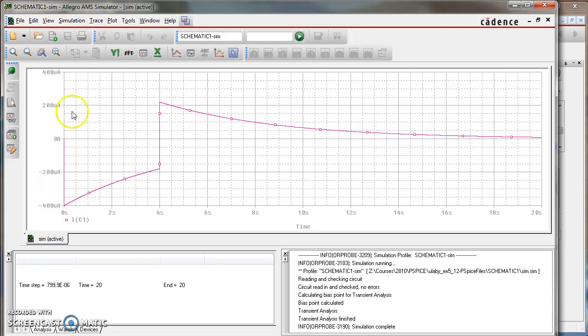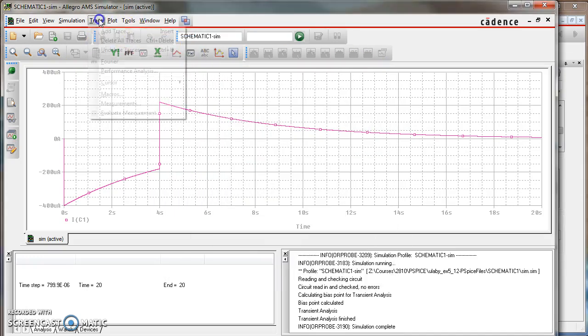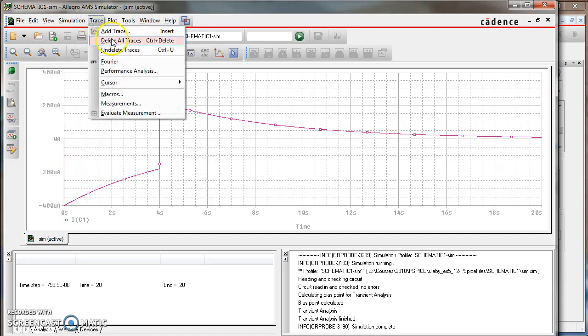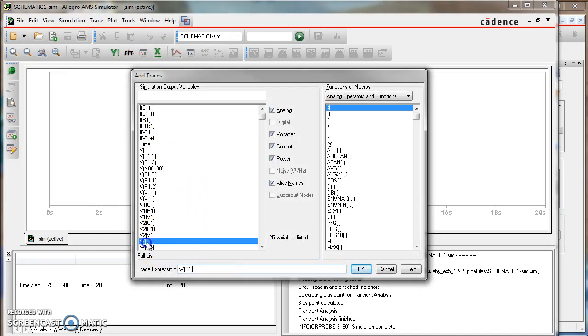Obviously the capacitor is going to be charging up during the cycle with pulses high and then discharging. Okay. So it's telling us the current that's pointing from the capacitor going back into the source. So we can also look at the amount of power being supplied by the capacitor.